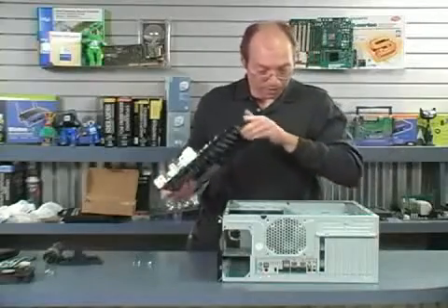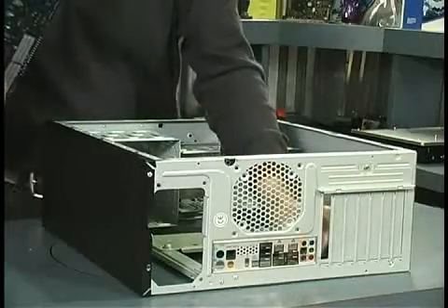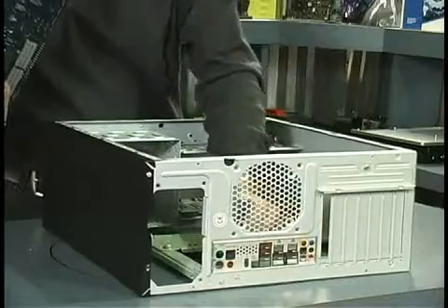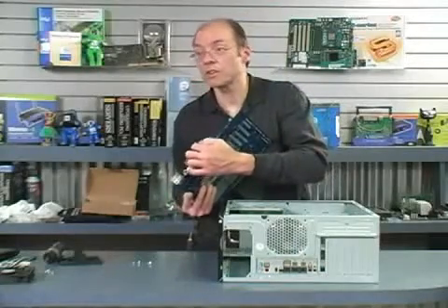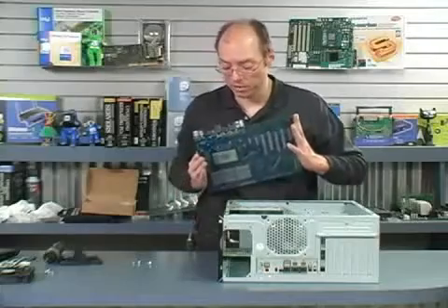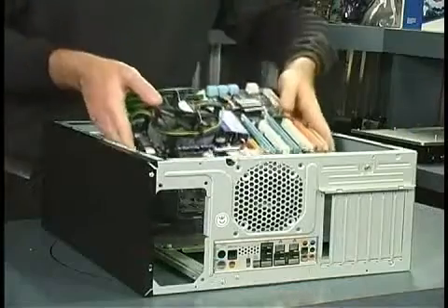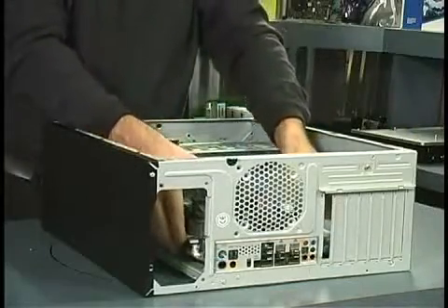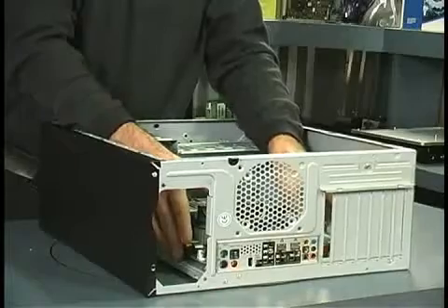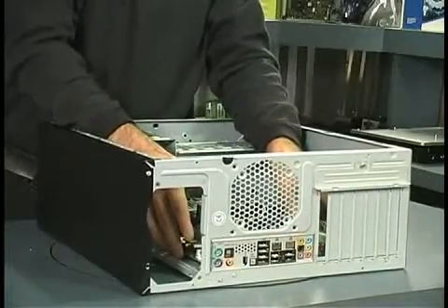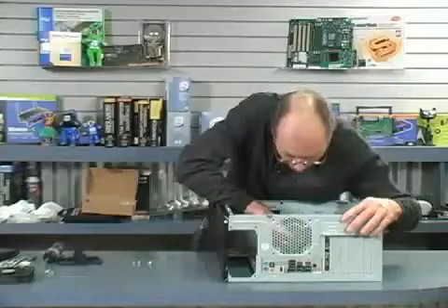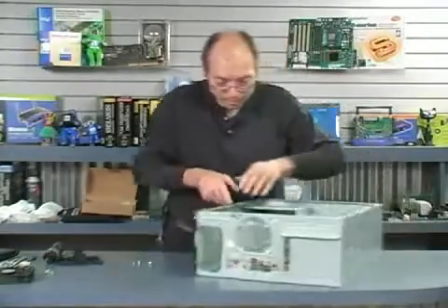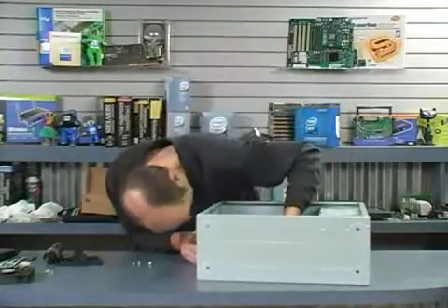Now, one thing you have to be careful with, there are some little grounding tabs that stick out on these I.O. shields, and they can get bent up, and I've seen them actually get stuck in or inserted into some of the ports here. So you want to make sure that doesn't happen as this presses up here. So I'm going to set this down, push it back, make sure all these connectors are lining up.